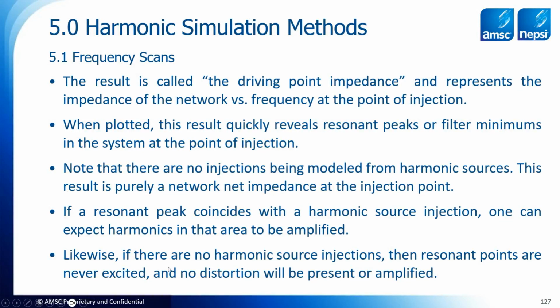Likewise, this is really, really key. If there are no harmonic source injections, then resonant points are never excited and no distortion will be present or amplified. If you have a system with no harmonic sources, there's almost no need to do a harmonic simulation. Harmonic work is typically for those systems that we know have some form of harmonic source involved.